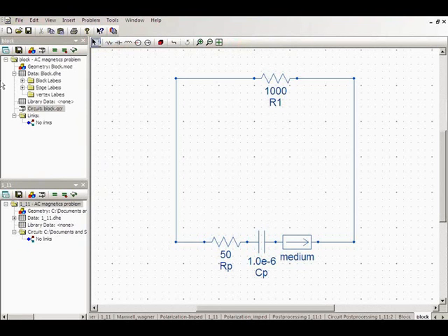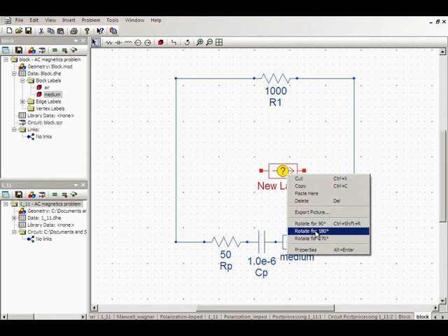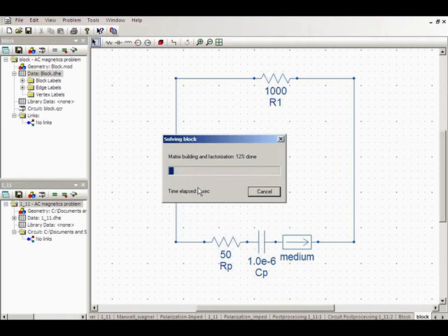Now in our circuit model, we have once again a polarization impedance because of the electrodes at the end, and we've also made a connection to the block here. The current flowing through our finite element model is connected to this circuit, and I was able to do that by inserting the block model here, where we can simply put in finite element components. Okay, let's solve the problem.